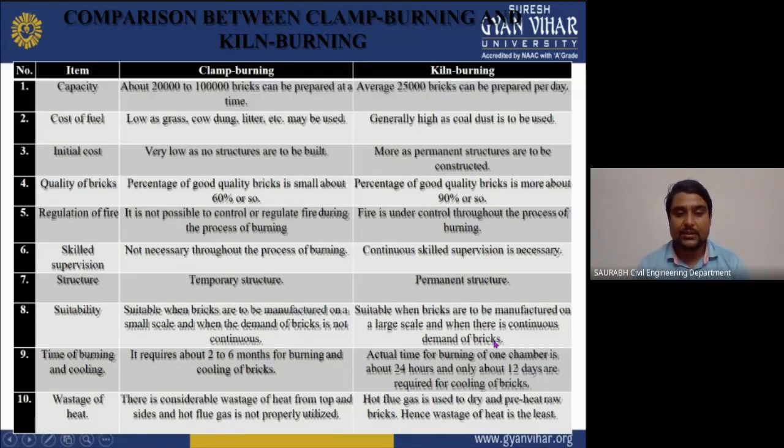Now we will see the time of burning and cooling. It requires 2 to 6 months for burning and cooling bricks. Here, what is the time duration for burning bricks in clean burning? The actual time for burning in one chamber is about 24 hours, and only about 12 days are required for cooling bricks.